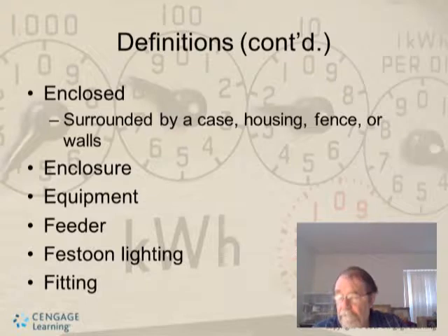An effective ground fault current path is an intentionally constructed low-impedance electrically conductive path designed and intended to carry current under ground fault conditions from the point of a ground fault on a wiring system to the electrical supply source.